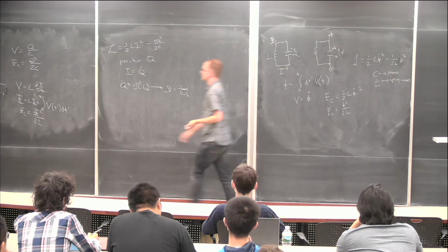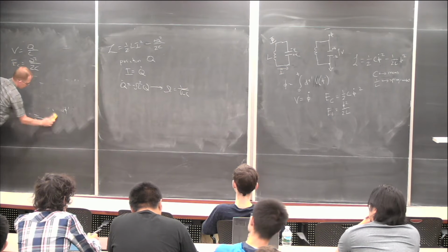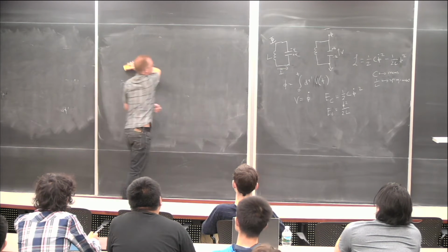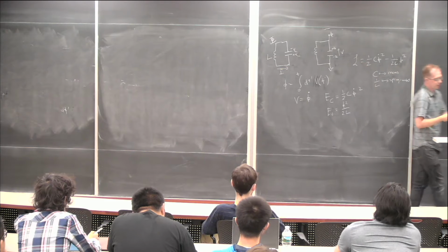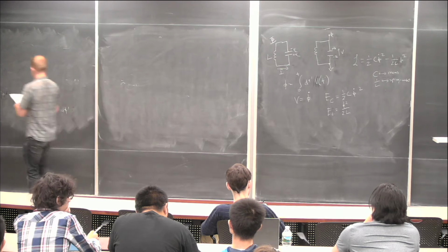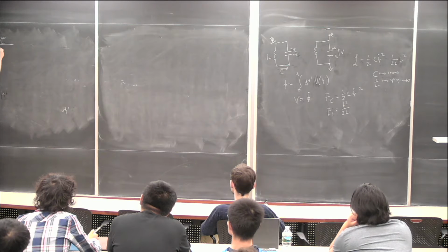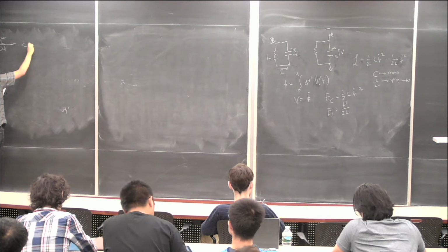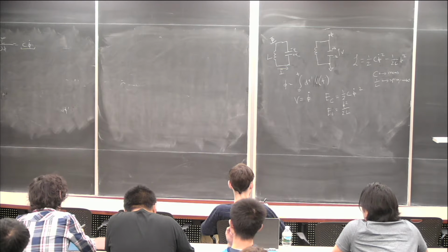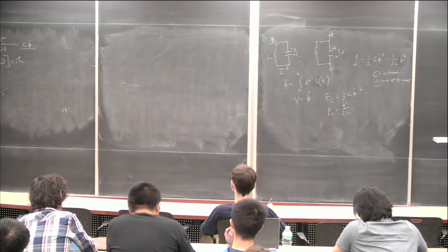It doesn't exist. Okay, so from there we can do things that you might expect and actually go about and quantize our circuit to give ourselves some happy one state. And to do that, we again can figure out what our momentum variable is. Our conjugate variable to flux is dL/d phi dot, which is equal to C phi dot. And so this is our conjugate momentum. And you can show that phi and Q have the right commutator relation.